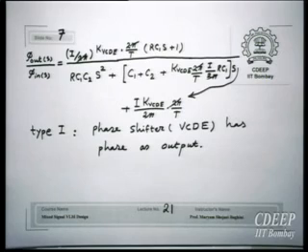So what is the use of this transfer function? This transfer function says that if there is some perturbation, some change in the phase of input, how this DLL loop will settle. Because here everything is constant. We are not changing frequency. We are not changing any phase at the input effectively. But this says that if there is a perturbation in the phase of input, how it will settle. So that is the only effective use of this transfer function.